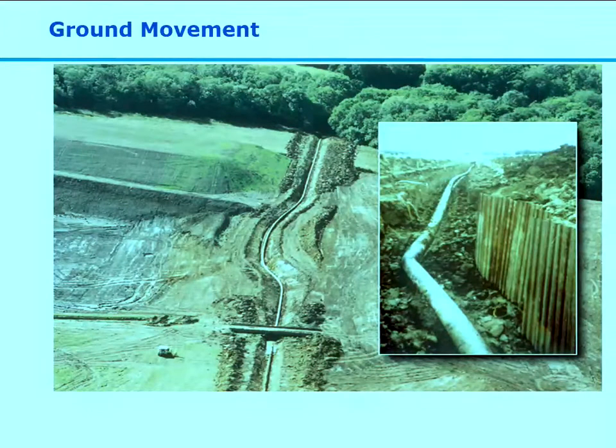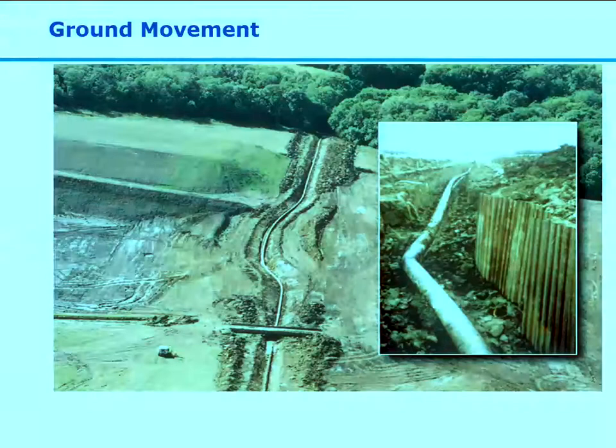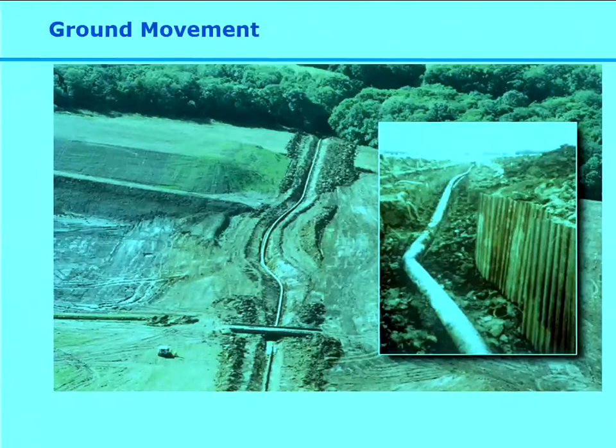So at the time when this happened, this pipeline was a critical supply pipeline for the southeast of England, and so they didn't actually want to decommission the pipeline. So what they did was they excavated it to remove the loading on the pipeline, and they reduced the pressure so that they could operate the pipeline over the winter and then repair it in the following year.